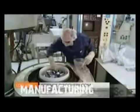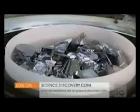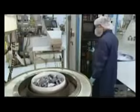It took decades to perfect the process of producing silicon with a perfect monocrystalline structure. They begin with raw polysilicon, or poly, and heat it to over 2,500 degrees Fahrenheit inside a special sealed furnace, which has been purged with argon gas to eliminate any air.